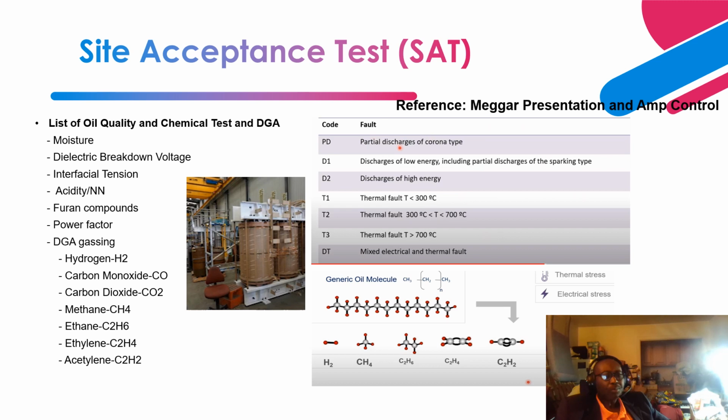Next is dielectric breakdown voltage. Okay, so that is the testing that basically tells you the withstand of the oil to be able to withstand lightning impulse voltage, switching impulse voltage, and power frequency over voltage conditions.